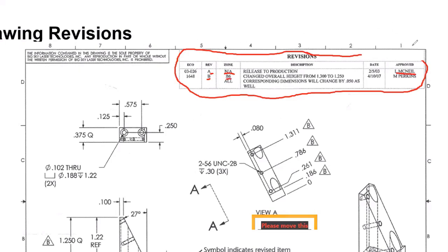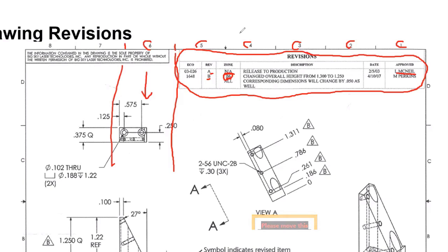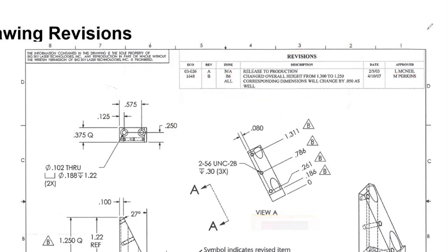B6 means, if you look around the frame, you have the rectangle frame with numbers 1, 2, 3, like checkboxes, then 4, 5, 6. Region 6 is from here to there, so I go to the zone with this region. We have B6 here, so you have to go there and find the B. In the vertical side also we have